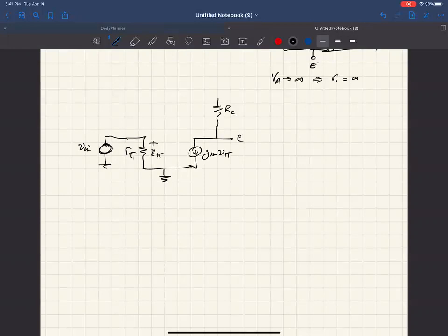And then also, if you remember, going from large signal batteries, you would assume that anything that is not perturbed is zero. So basically, this would be a 0 voltage battery, which is basically a short. That's why we got rid of the biasing element here, and that's also why we connect the R sub C to the ground.